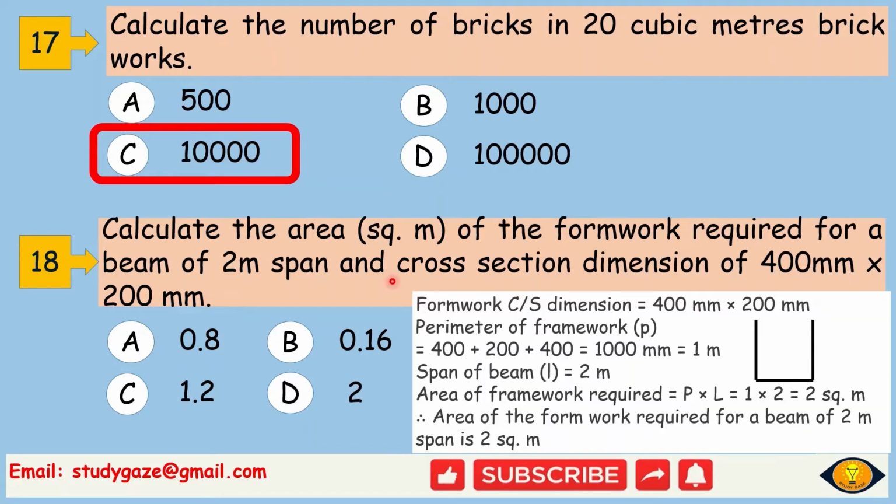We can see here, if this is the formwork of the beam, the depth will be 400 mm and the width will be 200 mm. Okay. Perimeter of formwork, we have to determine the perimeter into length of the beam, that will give you the area of the formwork required. Okay. So what is the perimeter of the formwork?